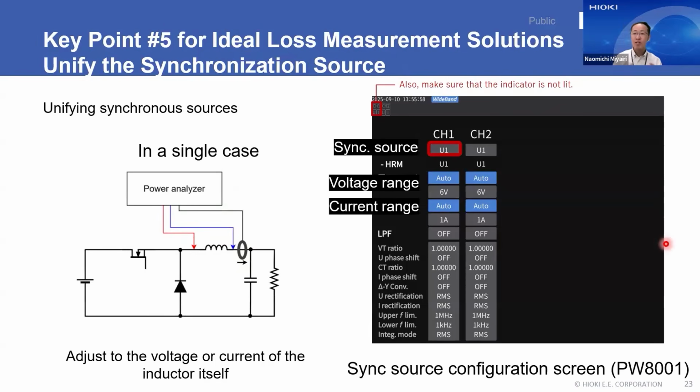When measuring a single inductor, synchronize the measurement to the inductor's own voltage or current. So during measurement, please check the channel indicators on your instrument to ensure there are no synchronization errors.